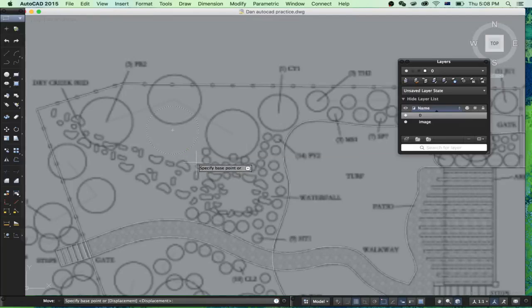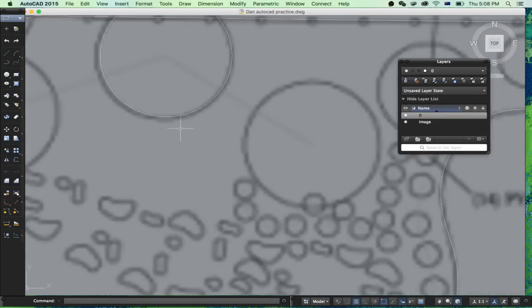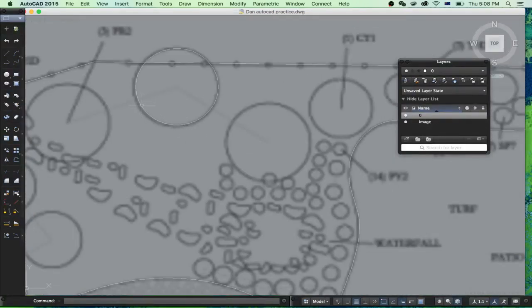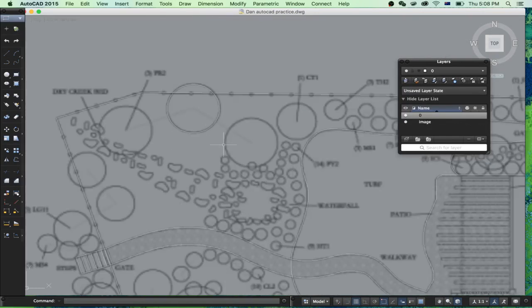I want to move it from the center, so I have to put the mouse on the edge, then I get the center point, and then I can come and go like that. Okay. You might say that's a little bit small, so let's do it again. Let's make it 5.7. Circle, click, 5.7, select, move, come to the edge, then you see the center point, and then you can move it into the place.